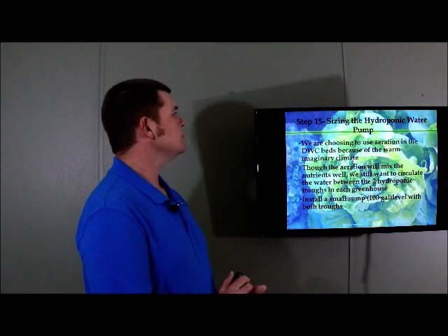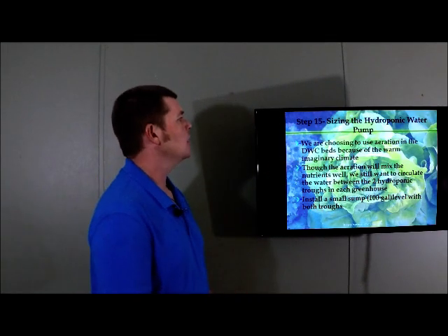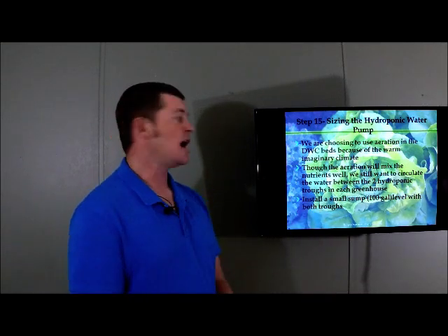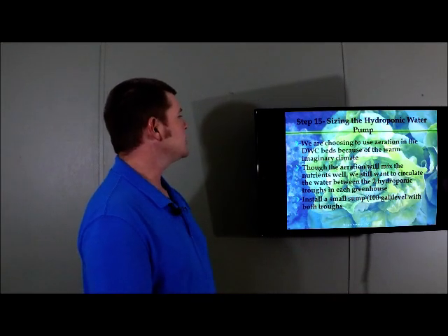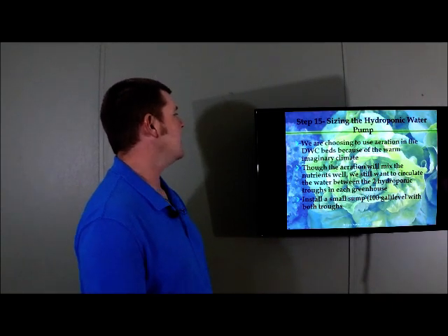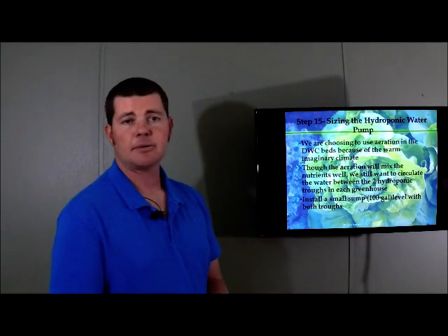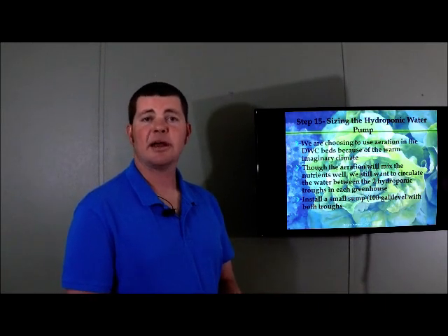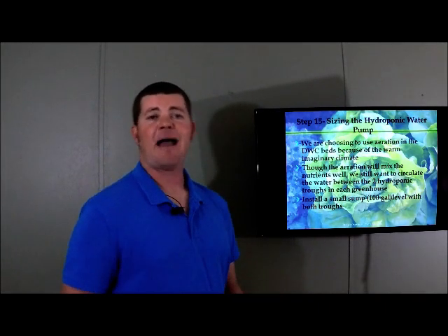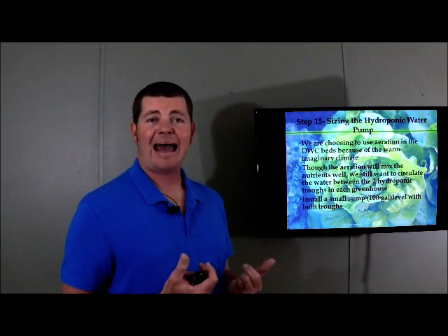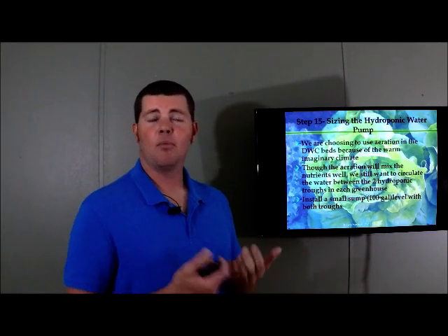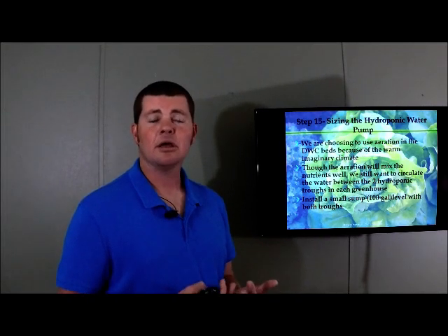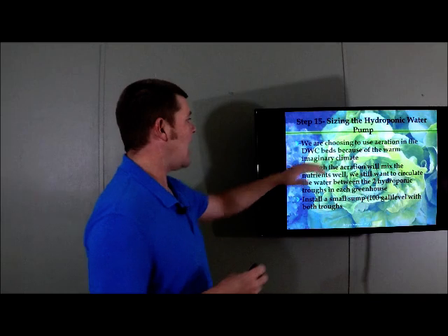Now we're going to size the hydroponic water pump. Okay, we're going to move over to the plant side. We just finished the fish side. We're choosing to use aeration in the deep water culture beds because of the warm imaginary climate, okay? And in a warmer climate, it can work real well to use aeration, and we can use that to evaporate some of that water out of the troughs, helping to get more humidity in the air, which is going to cause evaporative cooling in this theoretic hot environment.